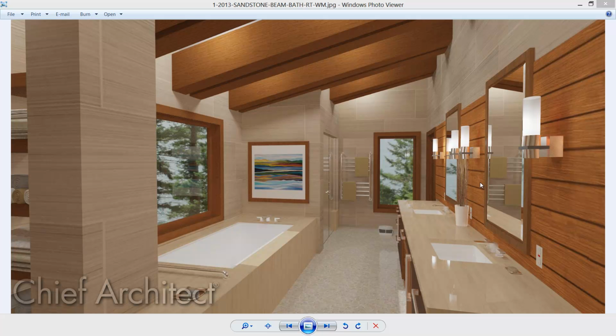The final structural thing that I want to do for the bathroom is add in our beams. And you'll notice that these are a timber frame off of an open ceiling that's been vaulted. I'm going to go ahead and place our roof on our plan here, and I'm going to create that at the 3 and 12 pitch. Let's look at how to do that.